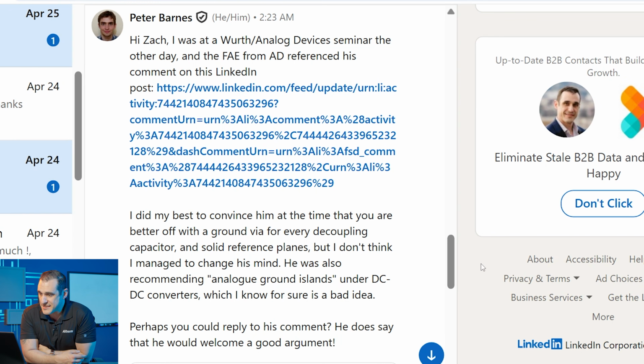Let's take a look at Peter's LinkedIn question. Peter writes, "Hi Zach, I was at a Worth/Analog Devices seminar the other day, and the FAE from Analog Devices referenced his comment on this LinkedIn post." And here he gives us the link to that LinkedIn comment. "I did my best to convince him at the time that you are better off with a ground via for every decoupling capacitor and solid reference planes, but I don't think I managed to change his mind. He was also recommending analog ground islands under DC-DC converters, which I know for sure is a bad idea."